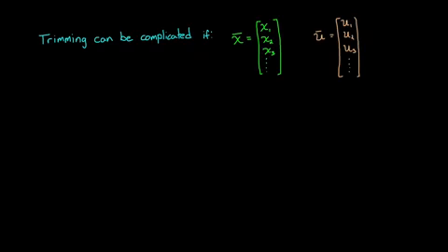You can imagine trimming can be a complicated task if your system has dozens of states you're trying to hold constant and several control inputs that you can use to control them. In the next video, we'll talk about some of the tools available within Simulink to make trimming easy. For now, though, it's enough to understand the concept of trimming and how it relates to producing a steady-state operating point. At this point, let me go off on a real quick aside.